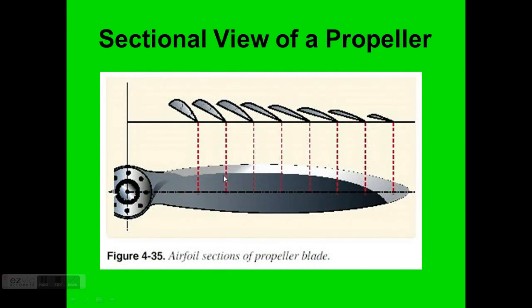Okay, so if you look at this airplane propeller, if you were to cut this airplane propeller at this point, you'll have a flat section along the back and a rounded corner along the top. And as you go out through, you'll continue that effect. So as this propeller spins, the air in front of the propeller has a longer distance to travel, less air pressure in front of the propeller. More behind it, it pulls your airplane through.